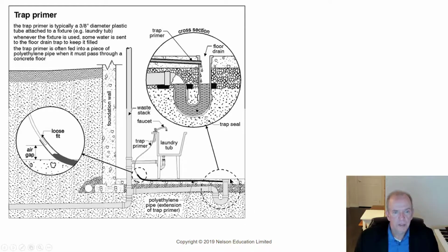Another thing that helps a lot is modern furnaces that are high efficiency. They have condensation build up in them, and the condensation usually has a plastic pipe that goes to the drain, because in modern houses, they put the furnace near the drain, or more realistically, they put the drain near the furnace. The furnace should be central to the house, kind of.